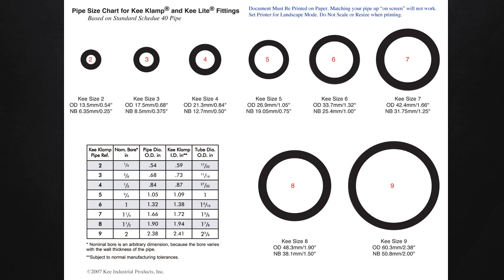The outer diameter for all schedules for the specific nominal diameter remains the same, and it is the internal diameter that is adjusted according to the specific schedule. You can see that the specific schedules then relate to specific wall thicknesses, which in turn relate to a maximum working pressure.